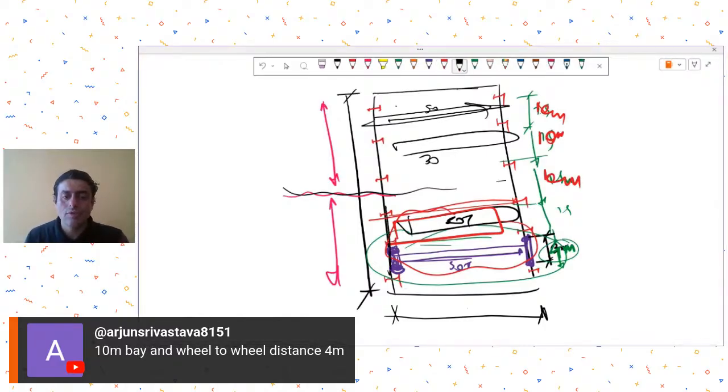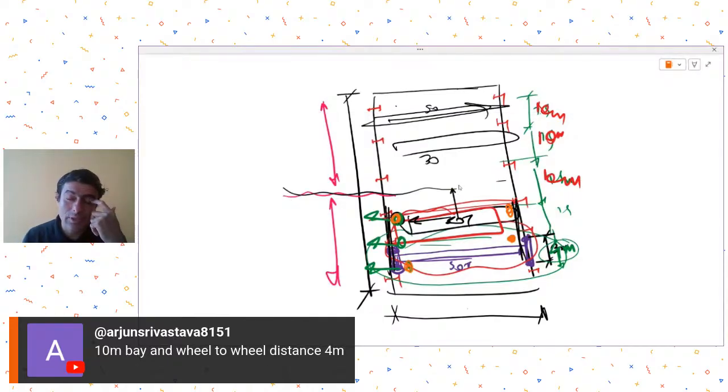So accordingly, first of all, you need to check for your crane girder. When it comes to the impact loads, longitudinal and transverse, you have to consider the possible positions of the crab. Sometimes you may consider all three crabs are over here; in that case, take the lateral load for your design. Then you may consider one crab here, two crabs here. Then one crab here, one crab here, one crab in the middle. So all these different load cases you may have to make.